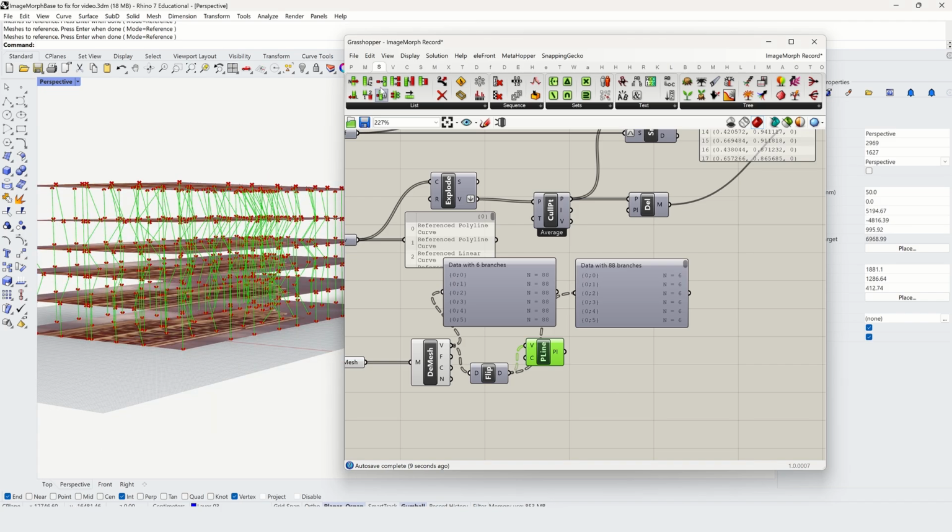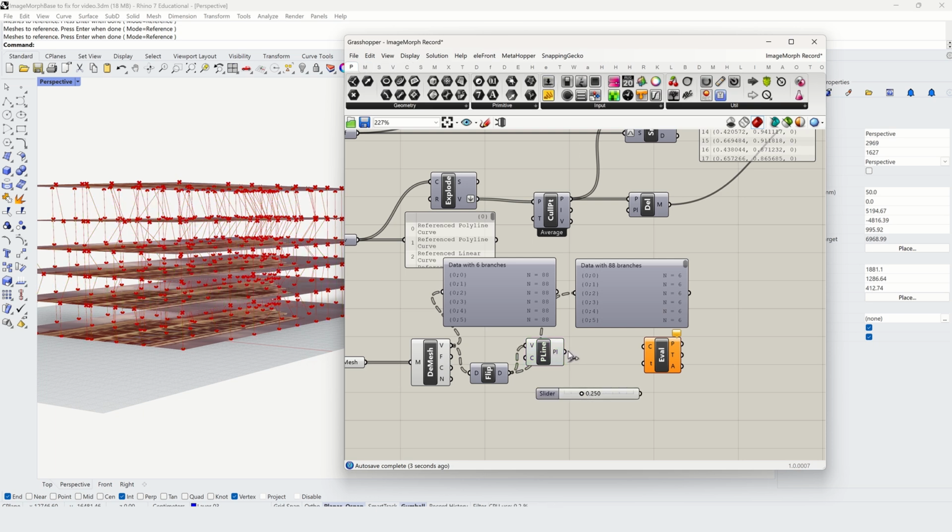To actually follow along these curves, we'll use an Evaluate Curve component and a number slider from the Params tab. Evaluate Curve has a T input, and in the same way that the UV coordinates were like an XYZ grid embedded on a surface, T values are like a number line stretched over a curve. The slider and Evaluate component is a very common combination.